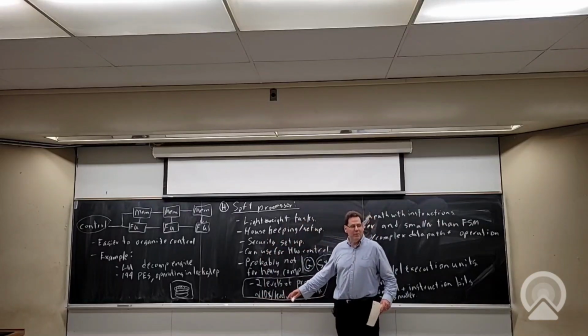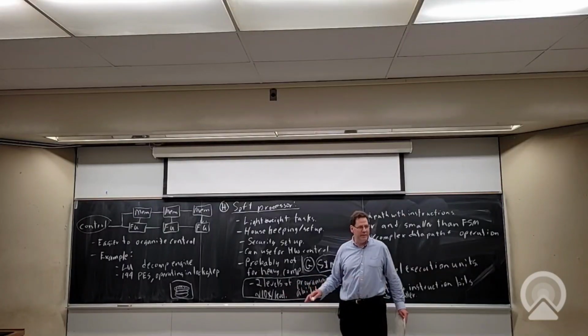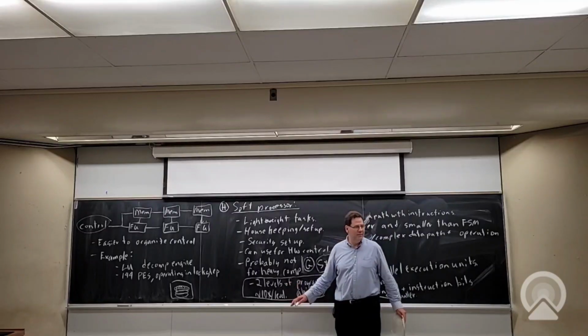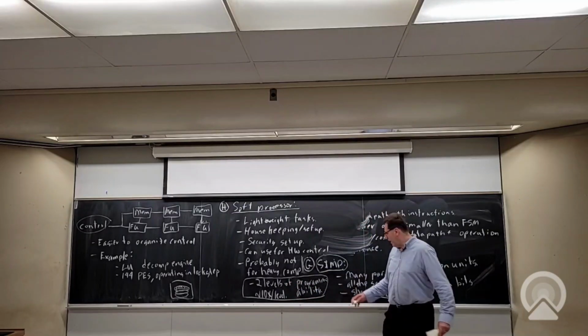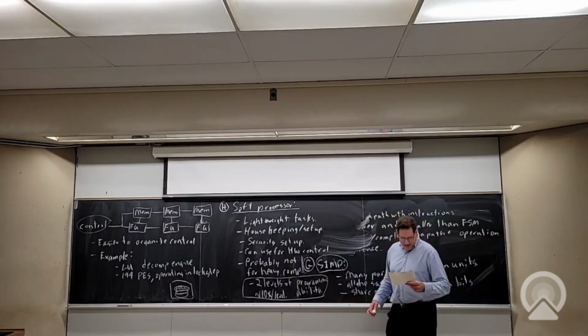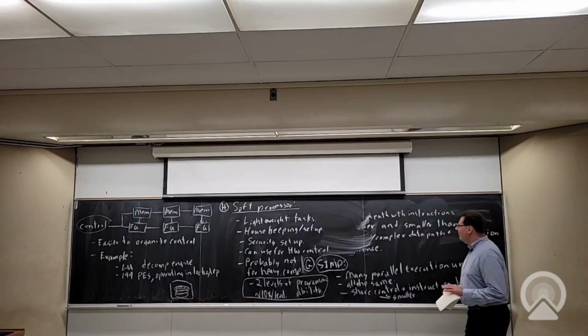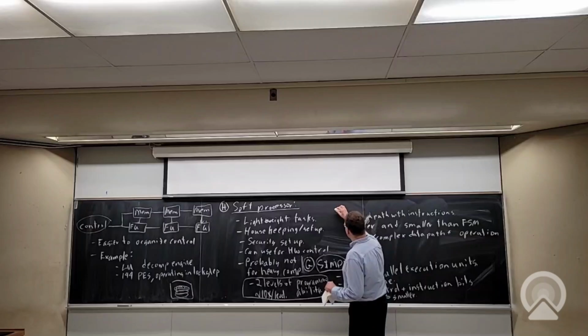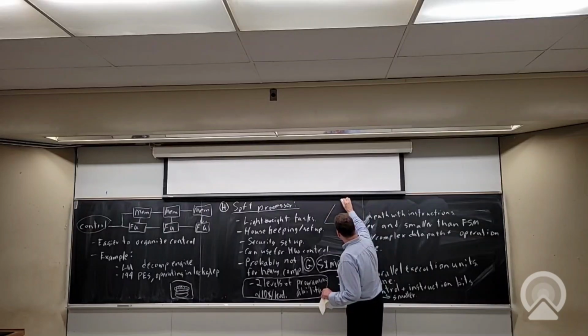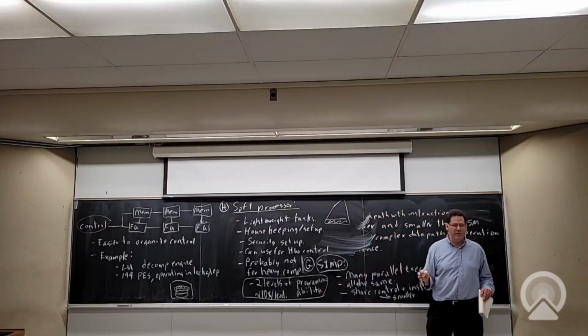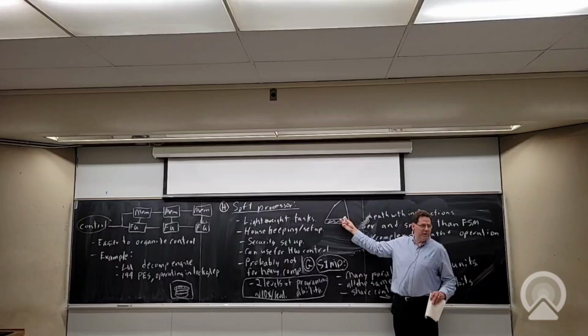So for order of magnitude, if you want to think of what is the cost of making something programmable versus hardwiring it, it's around 10x. Okay, so this is around 100x. There's one academic paper that I once saw, which amused me because what they did is they took an FPGA, a real FPGA, like a Xilinx or Altera FPGA. So it's programmable. It's lost maybe 10x efficiency versus you make all the gates.